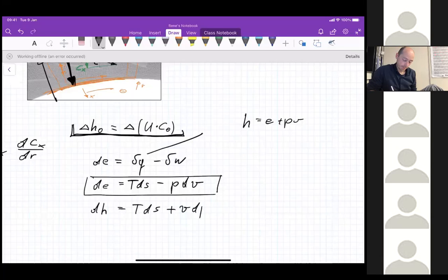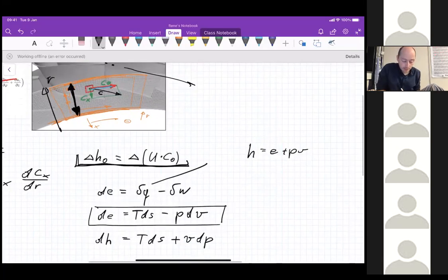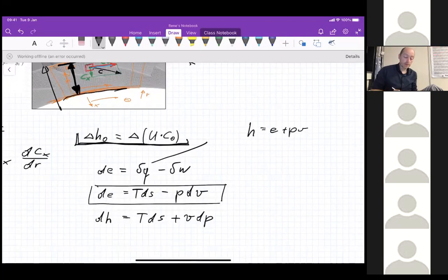dP. And we made an assumption before already, right? So if we say that we have no boundary layers that we want to take into account here, and we also say that we have no shock waves, then the flow is isentropic. No viscosity, no shock waves, no combustion, no reaction, and no whatever and whatnot. And it's also perfectly insulated. You have no heat losses across the system. Then the dq is 0 and TdS is 0.